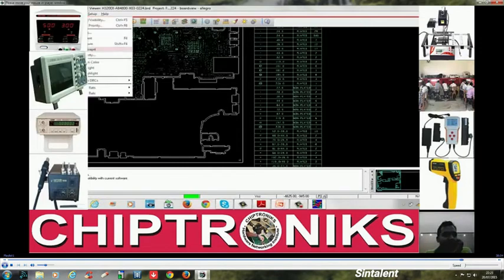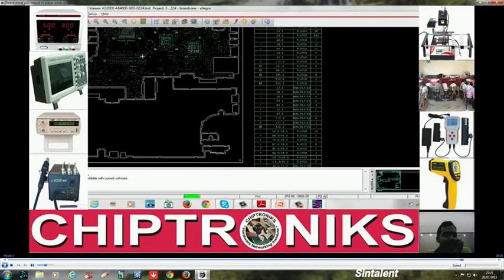In display, we can go into highlight, and we can highlight devices. You highlight, see, this is VGA DDR3 highlighted. Let's highlight this. This is ground highlighted. Let's highlight this, N873797, and you can do many kinds of stuff.